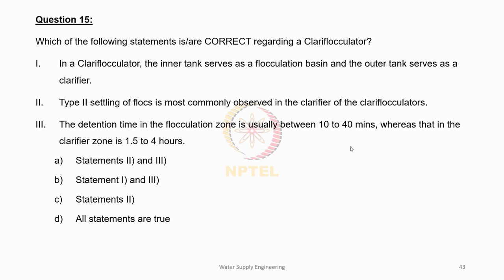Type 2 settling of flocs is most commonly observed in the clarifier of the clariflocculators. Statement 3. The detention time in the flocculation zone is usually between 10 to 40 minutes, whereas that in the clarifier zone is 1.5 to 4 hours.